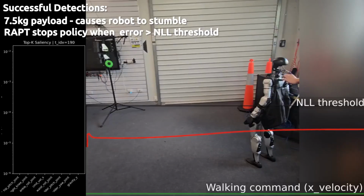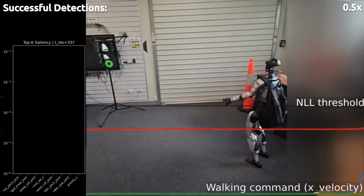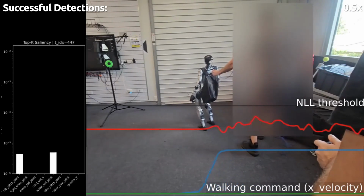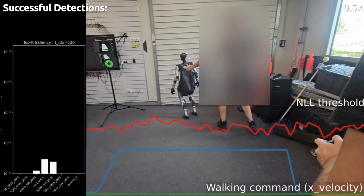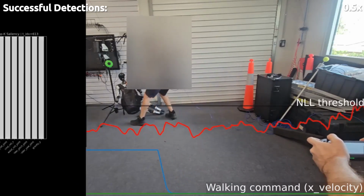This clip shows a real-world deployment with a 7.5 kilogram payload, far beyond the 3 kilogram maximum seen in training. Along the bottom are the commanded walking velocities, while the center plot shows the minimum distance to the calibrated anomaly threshold over time. On the left, we visualize post-hoc temporal saliency computed via backpropagation through time. Several seconds before failure, RAPT attributes the anomaly to hip pitch and waist roll, consistent with the robot leaning backward and laterally under excessive load.